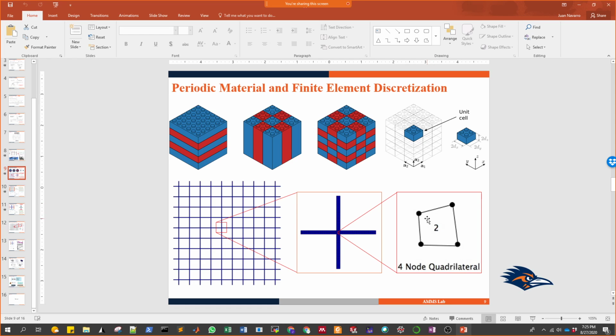Basically, we only find the solution at certain positions inside the element. We multiply the solution by certain weights, and then we do a summation, and that's it. We find a numerical way of finding an integral. In other words, you don't have to actually solve the integral by yourself. You just use a numerical method to do so.